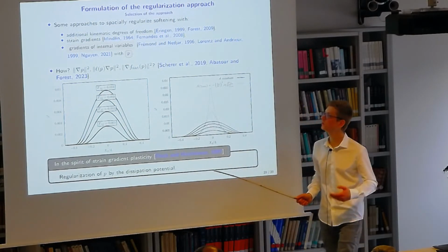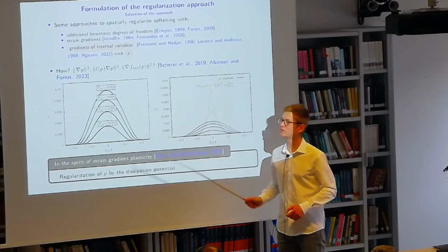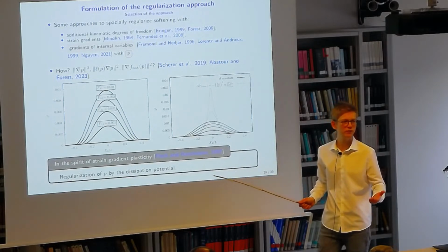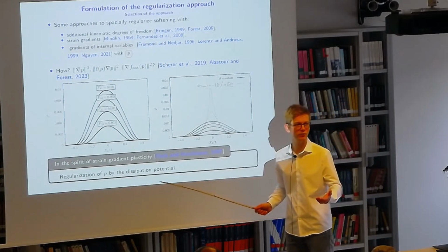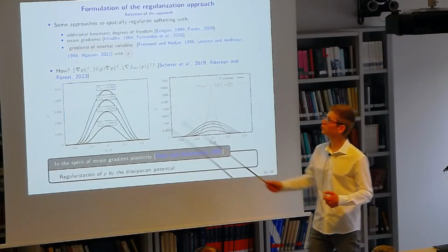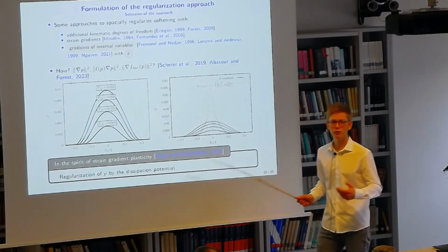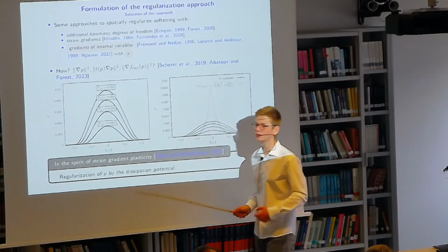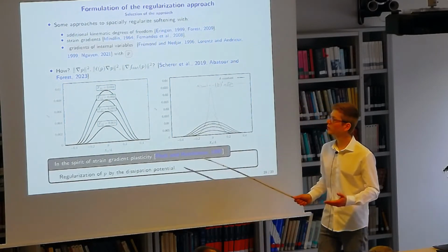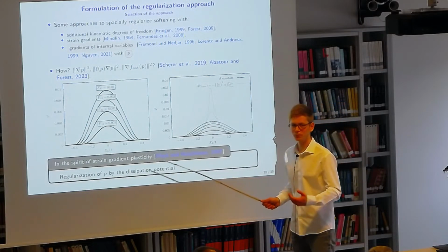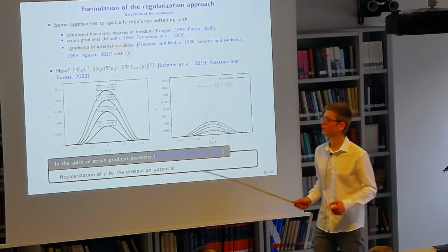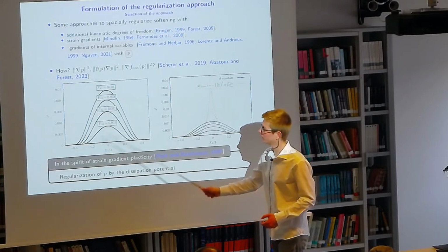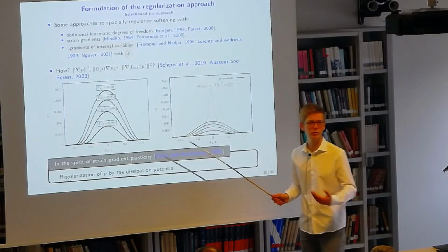And the one which is going to be selected is the cumulative plastic strain. In general, this is a positive increasing quantity with no finite maximum value. Therefore, we are aware of some difficulty if we just regularize it, for instance, with the square of its gradient in the free energy. One consequence is the phenomenon known as the spreading of the localization band, as illustrated on the left, with the size of the band increasing during the loading.